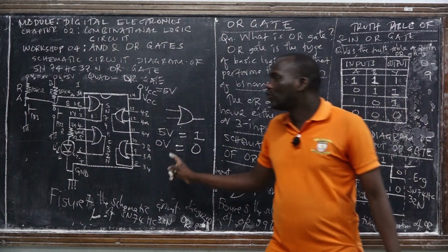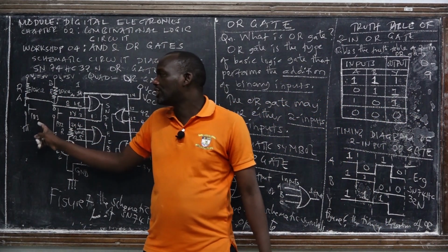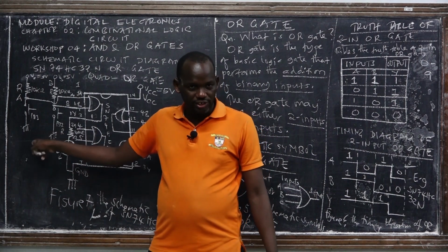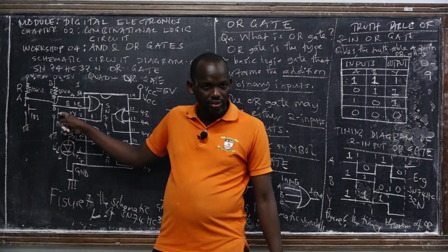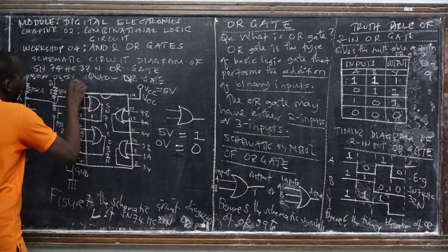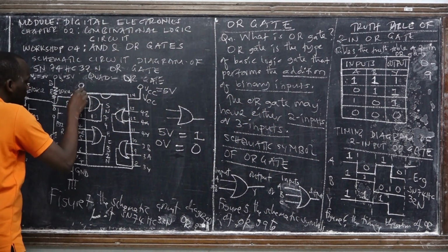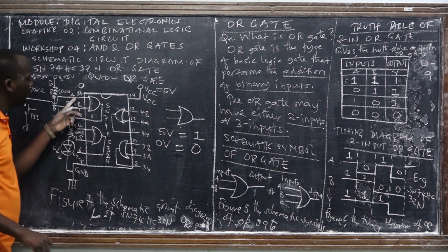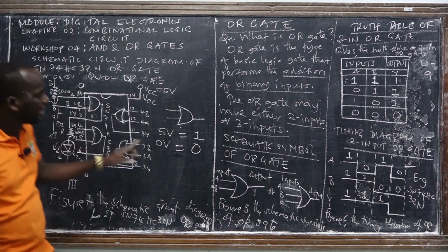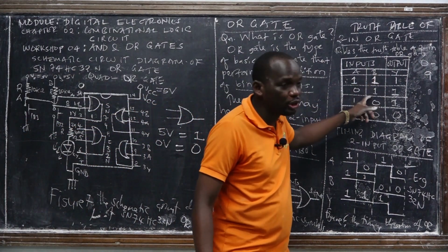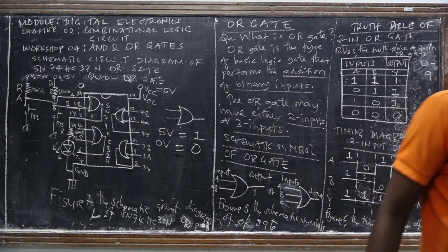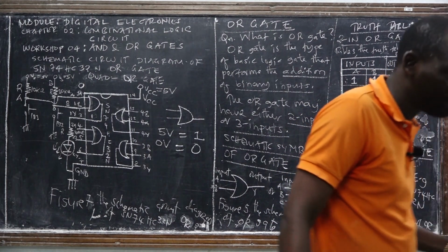How can you achieve it from the pull-up resistor network number 1? We press it. We have 0 volt, right? And then we have 0 bit for the input pin A, or input 1A. Then the status of input B is what? 1. How can you achieve it? Don't press. That is good. Press, don't press. Press, don't press.